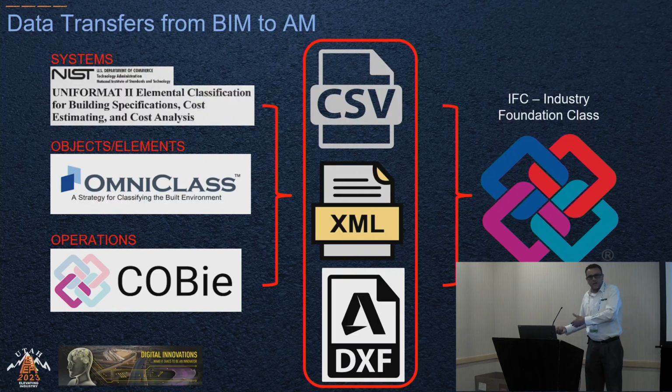So horizontally, we're starting to get IFC definitions, but we had to build our own IFC definitions, and I worked with our programmers and our data scientists to build IFC classifications for highway projects. So we have parent-child relationships, that hierarchy that we add and supplement and implement into the IFC models.